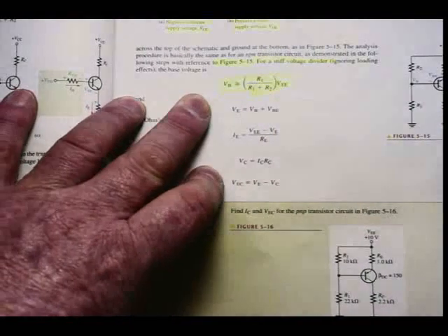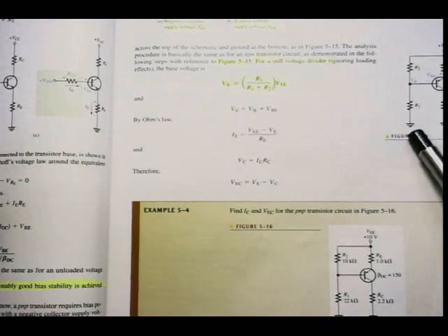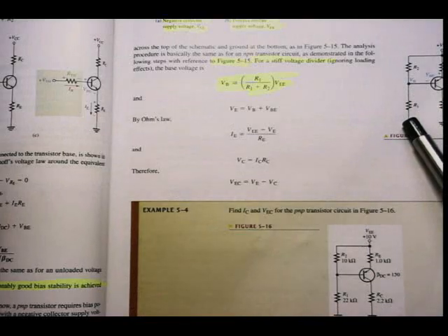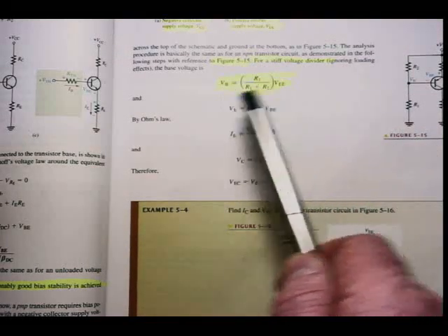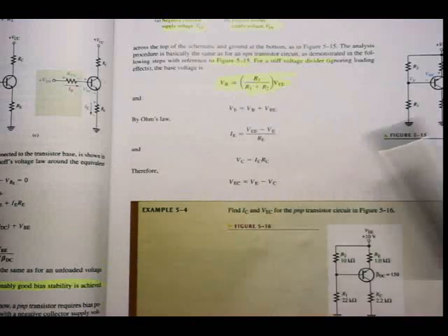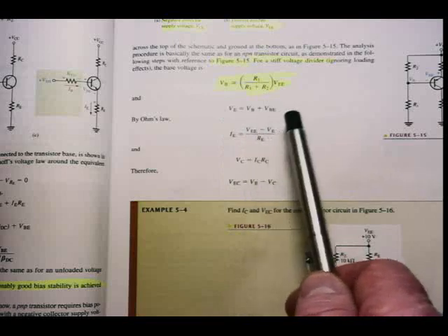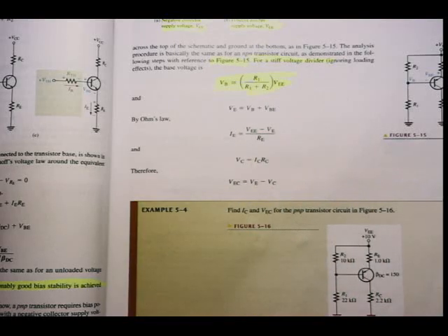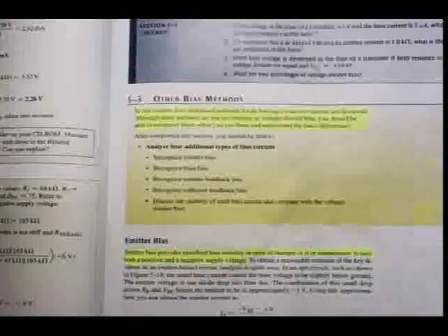But you can see now VB, but it still makes sense. VB is now going to be what? VB is still with reference to ground. It's still a single subscript. No? So VB is now going to be VR1 and not VR2 anymore. Okay, so it's going to be R1 divided by total resistance R1 plus R2 times VEE, the supply voltage. Okay, VE is still VB, in this case now, because the polarities change, plus VBE and so forth. Okay, but as I said, I want you to use the method.